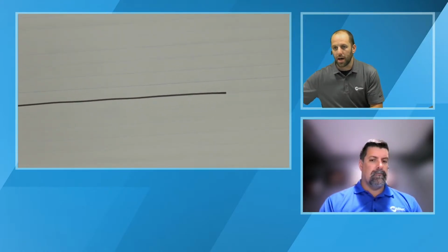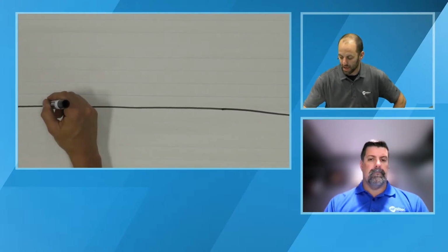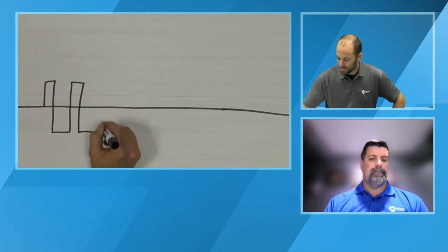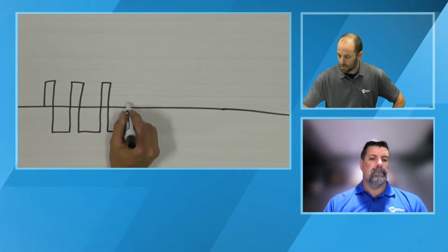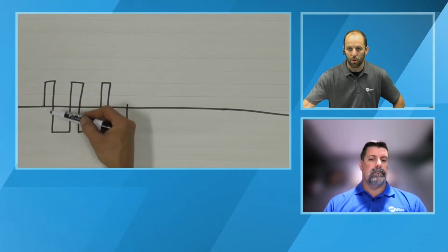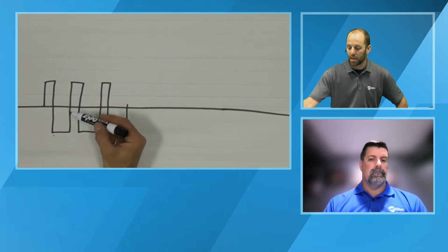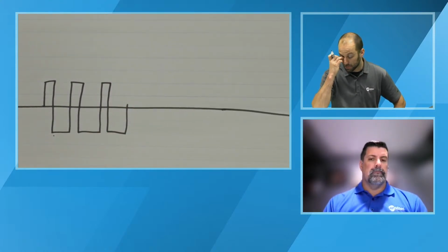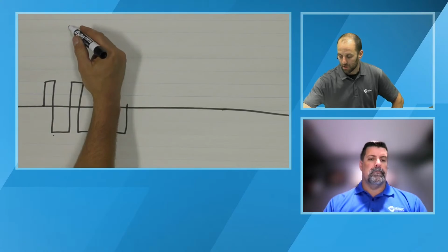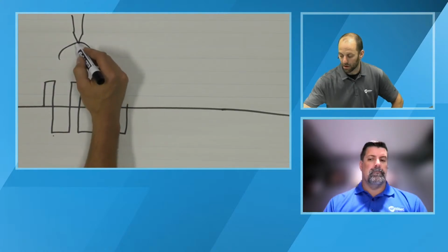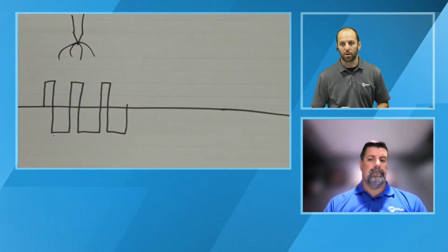Ultimately, if we think about what's happening in the AC waveform, we're going from a low amperage to a high amperage in electropositive, and a low amperage to a high amperage in electronegative. That switching back and forth between low and high is really what drives our arc cone to go from a wider arc cone down to a narrower arc cone.